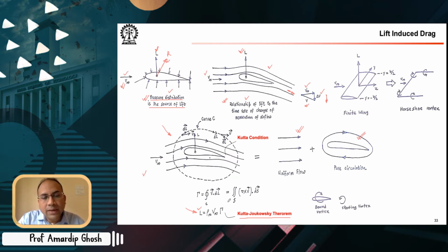And we will again, with these incompressible irrotational flow fields, use something called the velocity potential formulation, because if it is an irrotational field, then velocity can be represented as the gradient of some scalar, and that's the velocity potential. And we will see that, starting from that idea of velocity potential, flow over a rotating circular cylinder, and then applying Bernoulli's theorem to find the pressure distribution around the cylinder. And then, of course, lift is just the effect of that pressure distribution.